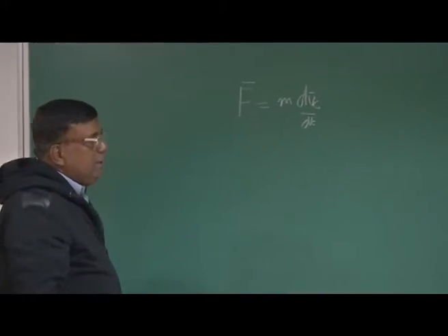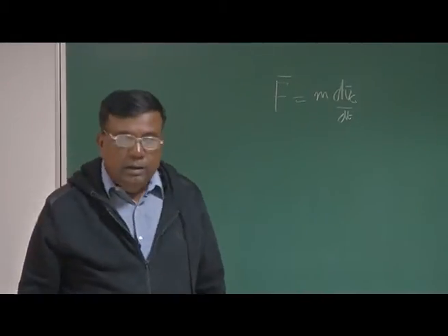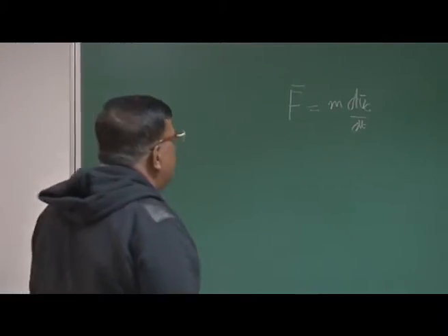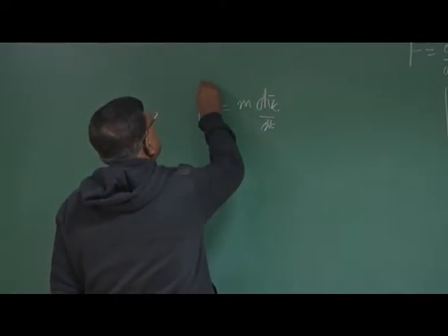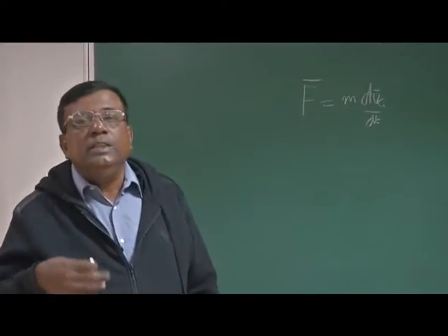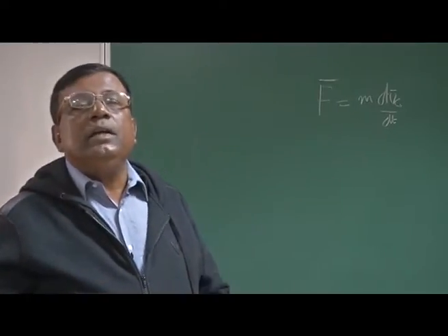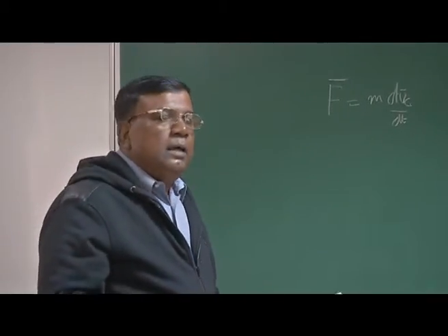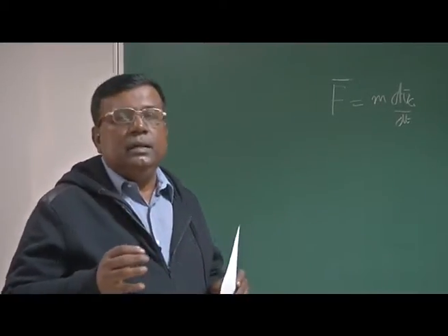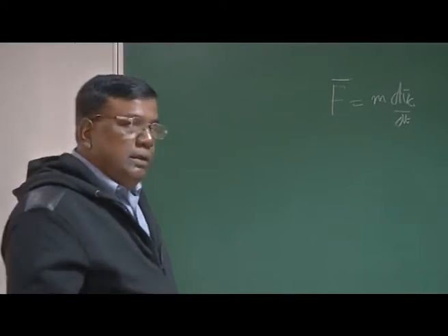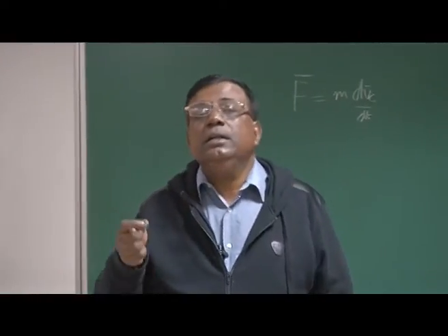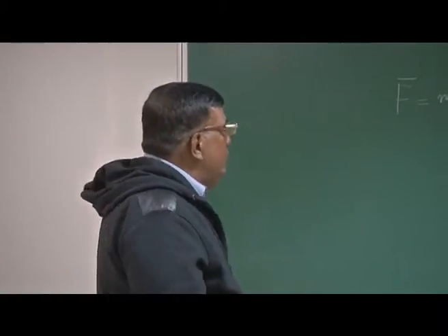Understanding was, whatever external impressed force is acting on the body, I can model it for a rigid airplane as if it is as simple as this: the external impressed force will change the acceleration of the center of mass. What is center of mass? Whatever we call the center of gravity on Earth, it is the point where all the masses can be assumed to be concentrated. Recall, we started developing this by assuming elemental mass, then did the summation, right? So, this is one understanding.